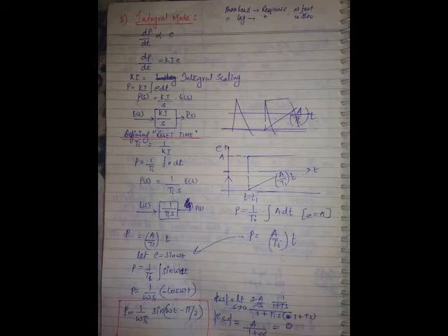Water will be falling continuously into the tank, and the water level also gradually starts rising at a constant rate. The error also is changing constantly. This is called a ramp error, represented as At.